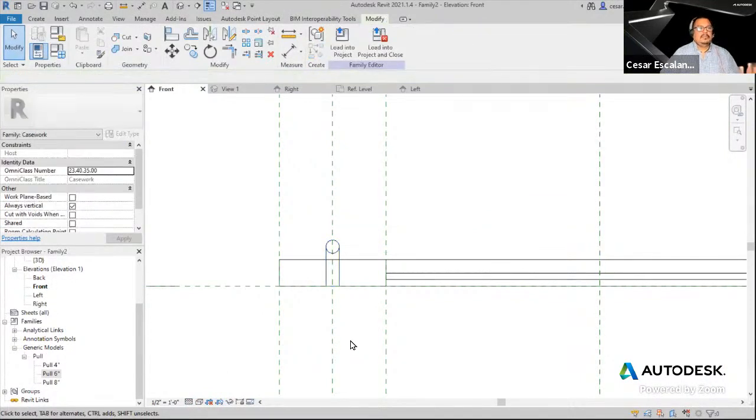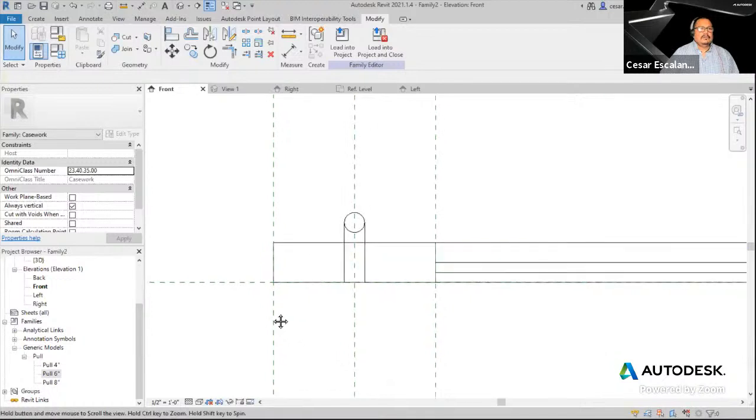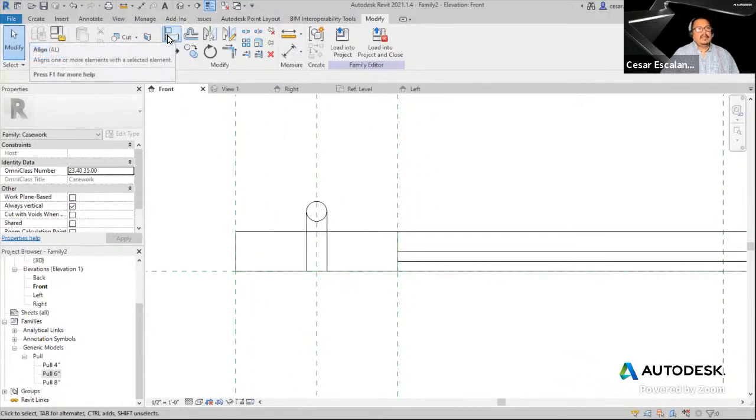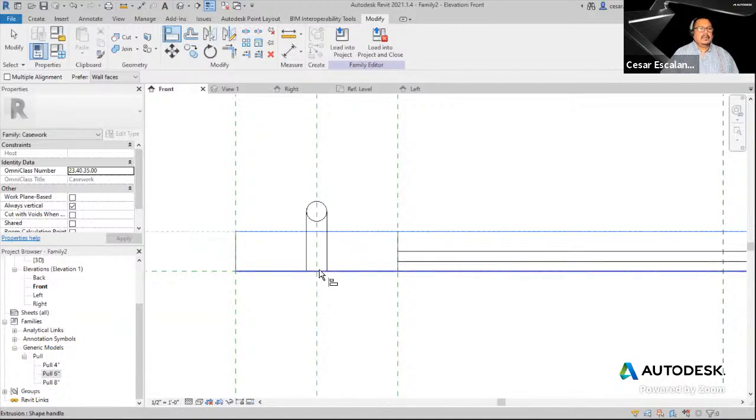And when I align something, I lock it. So I'm going to align to the vertical location of the pool. You've used this before. You hit the align tool, align where, to the face of the solid, align what. You hit Tab to select the lower face of the pool, and then you lock it. You have to lock it so that it doesn't move in the Z direction.